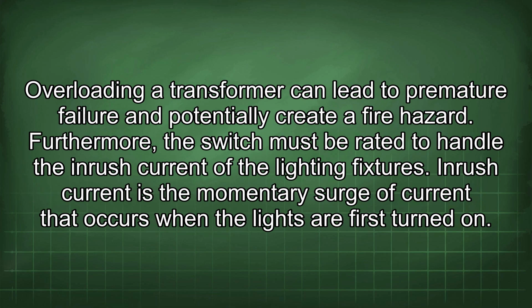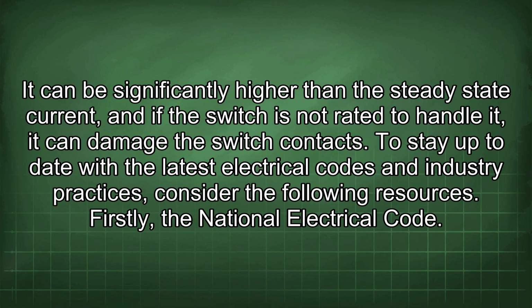Overloading a transformer can lead to premature failure and potentially create a fire hazard. Furthermore, the switch must be rated to handle the inrush current of the lighting fixtures. Inrush current is the momentary surge of current that occurs when the lights are first turned on. It can be significantly higher than the steady-state current, and if the switch is not rated to handle it, it can damage the switch contacts.